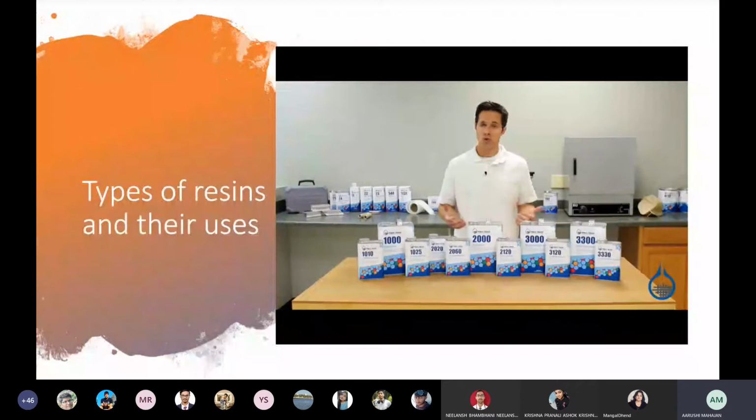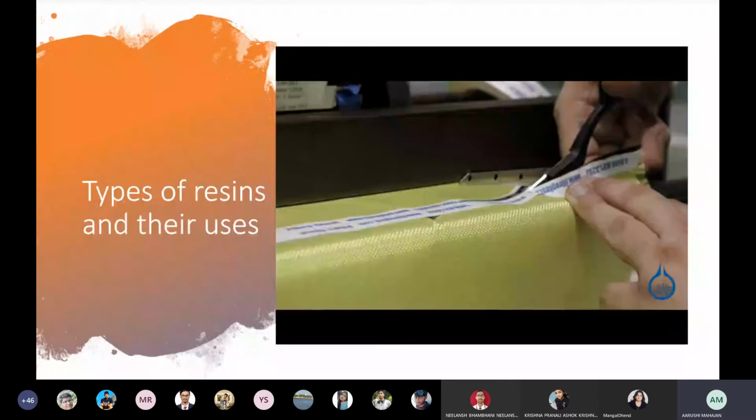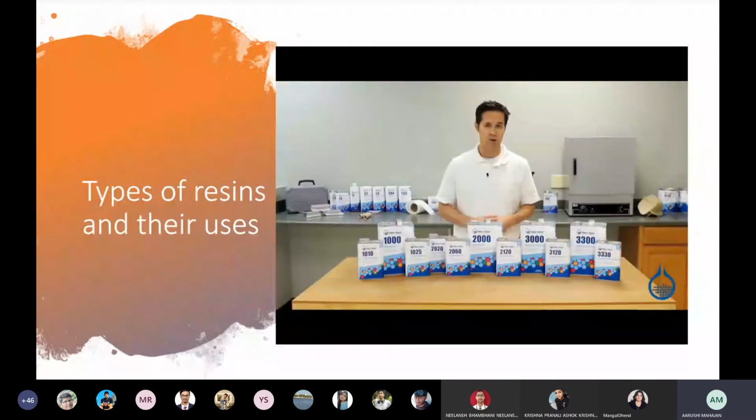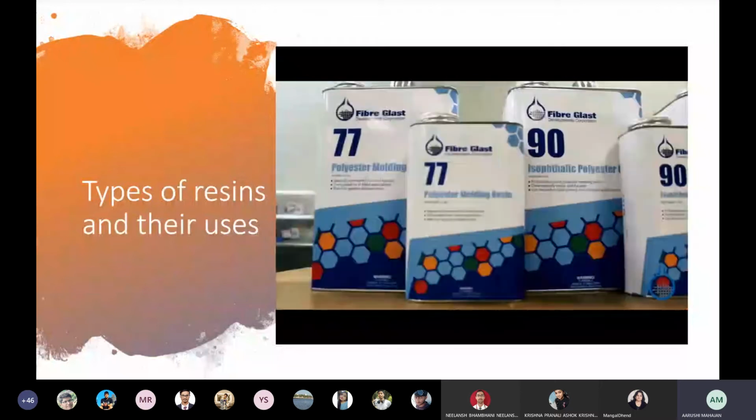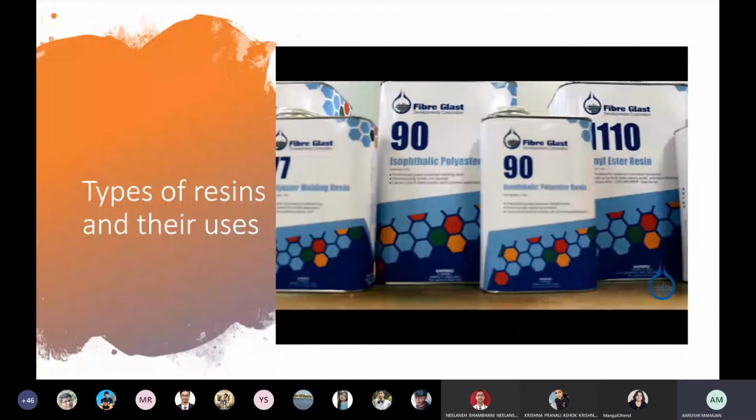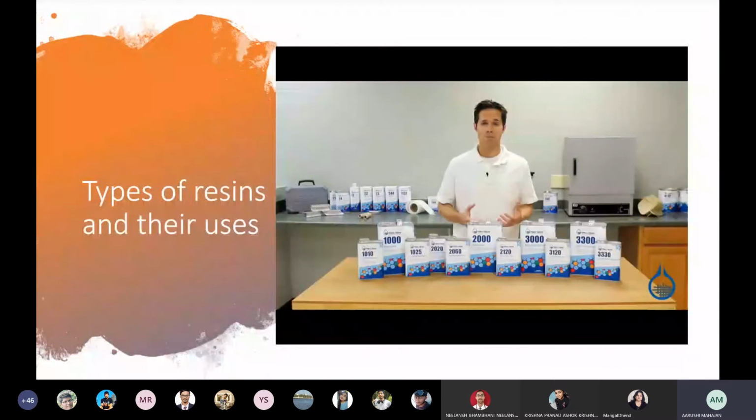Epoxy is the best resin type to use with carbon fiber and Kevlar reinforcements. These high-strength fibers are very difficult to bond to. The bonding of epoxy resins offer a strength that cannot be matched with polyester or vinyl ester resins. Epoxy resin also forms the strongest bonds to fiberglass fabrics and most sandwich core materials. This all adds up to epoxy resin being the primary choice for structural applications.